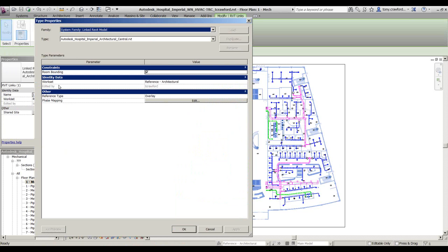I just offset them so that they're 3 feet above the floor or something. Yeah, so there are trade-offs. Again, it's do what you need to do. Or you could swap that family out to another one temporarily to show what you need to.